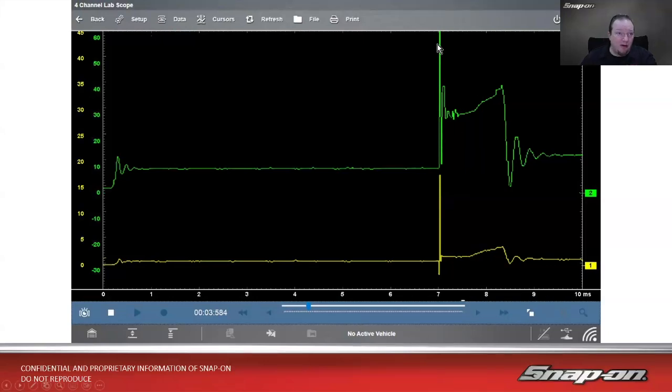This is just basically the voltage that would come out of the secondary ignition adapter, which, by the way, leads me to a question that I get asked all the time, because other scopes, when you do secondary ignition, are like, oh, well, you need to use an attenuator in there to drop the voltage down so you don't fry the scope. On ours, our ignition adapters are designed to work with our scope, and we don't have that problem of needing an attenuator in there because it sends out a pretty low voltage as it is, and then it just translates it to an actual, here's what it is in thousands of volts. It's not actually sending thousands of volts to the scope, right? But I can still get a pattern either way. It's just a matter of I get a lot more detail on the secondary.